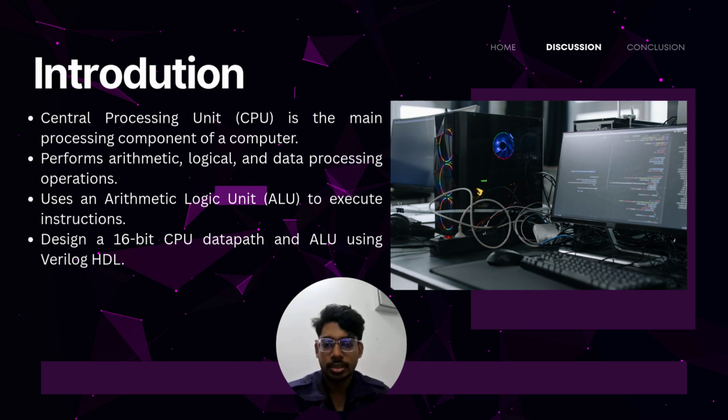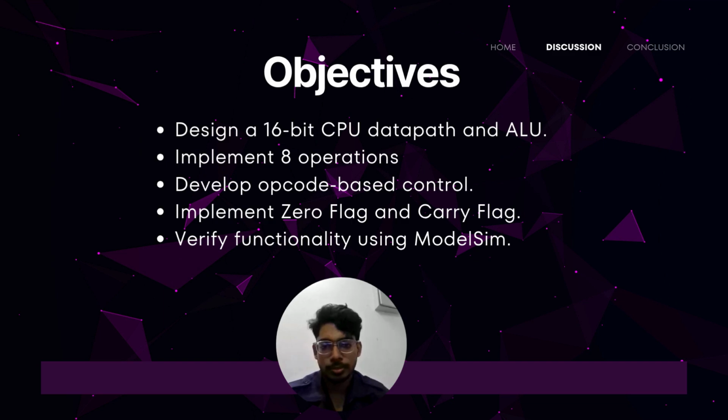As for the introduction, this is basically a 16-bit CPU datapath using 8 opcodes. The objective for this mini project was to design a 16-bit CPU, an ALU, and implement 8 operation codes, develop opcode-based control, and implement a zero flag and carry flag.